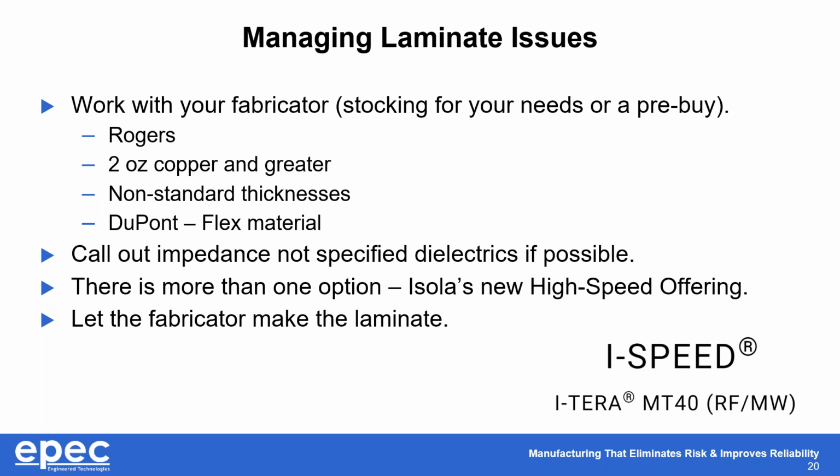One of the things that we're working with customers on now is, as part of your delivery or your stackup, if you specify and call out the impedance values that you want, it gives us a lot more options than if you just specify the dielectrics. If you specify the dielectrics and say we can't deviate from that because it's going to get you to a certain point, well, that's great. But the challenge becomes that now you've limited what we can get and how quickly we can deliver in some instances. So tell us what you want on the impedance side, and we'll tell you how we can get there and how we can deliver the quickest.